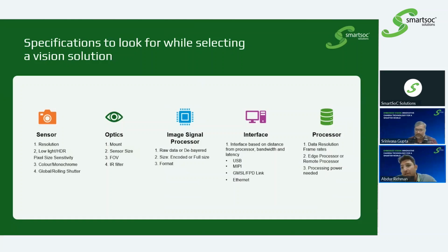Does this need to be done even when a machine is trying to understand this data, say for computer vision? There we can use raw data directly, because the entire information is available in monochrome. So there is no need for color. But where human interaction is required, there debayering is required.